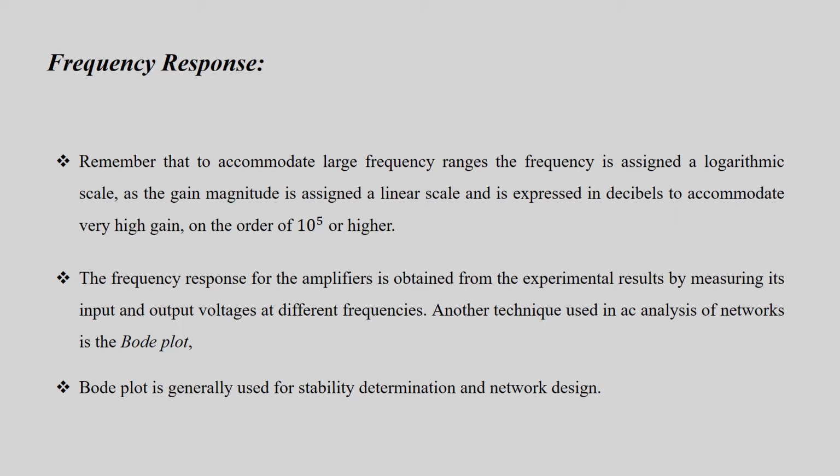Remember that to accommodate large frequency ranges, the frequency is assigned a logarithmic scale, while the gain magnitude is assigned a linear scale and expressed in decibels to accommodate very high gain of the order of 10 raised to the power 5 or higher.